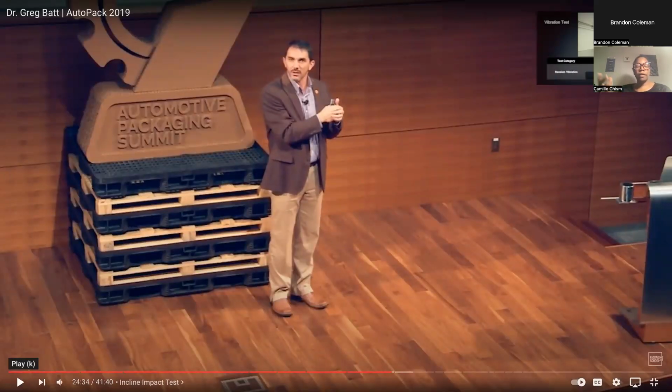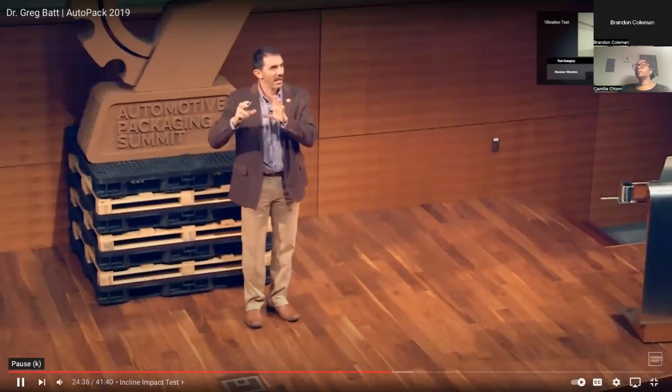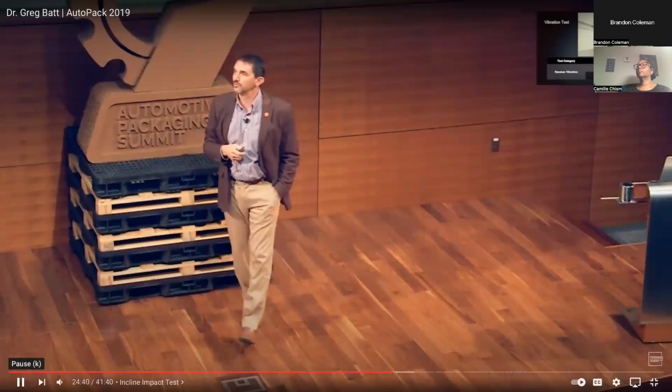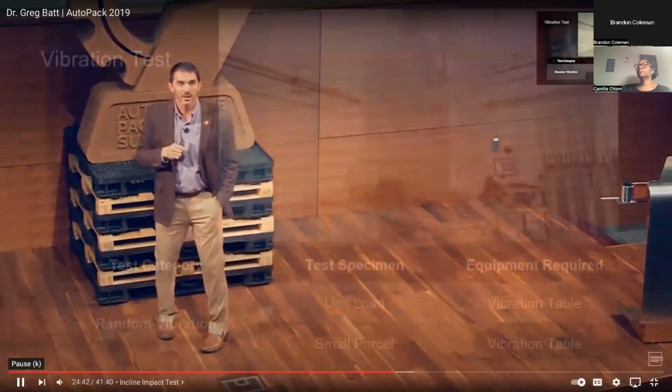We talked about that in chapter 3. So you want to balance capturing shock events or filtering them out and looking at long-term fatigue. Take that data and average it together, load that into our vibration system, and reproduce your truck ride.